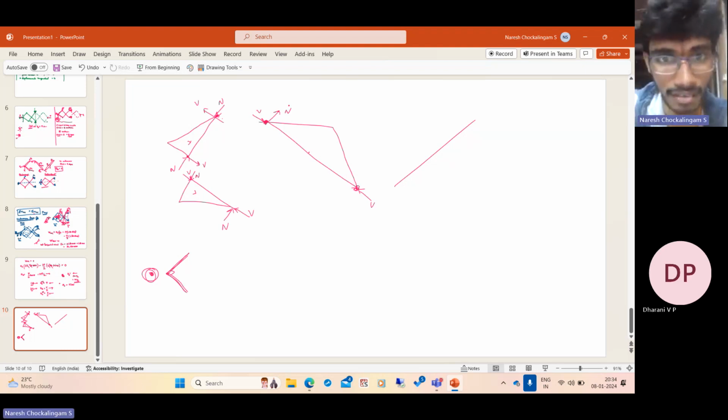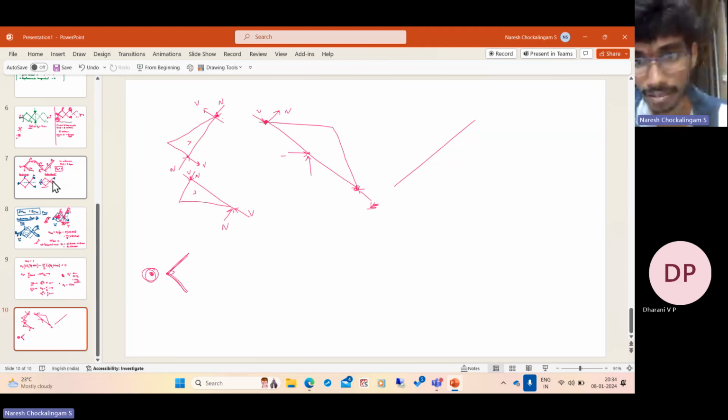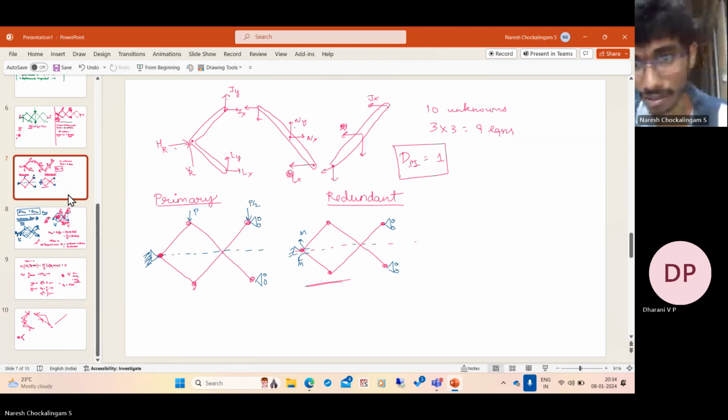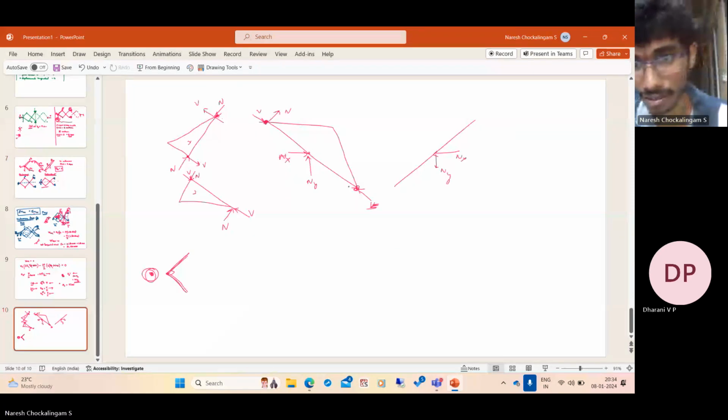Here the shear forces are not continuous. You can draw up to this point. Again, actually, this is also not continuous. So here there are some pin forces. You need to find them. Let us call these N pin, right? So this is NX, NY, and here you have the opposite direction, NX, NY, and then what else?